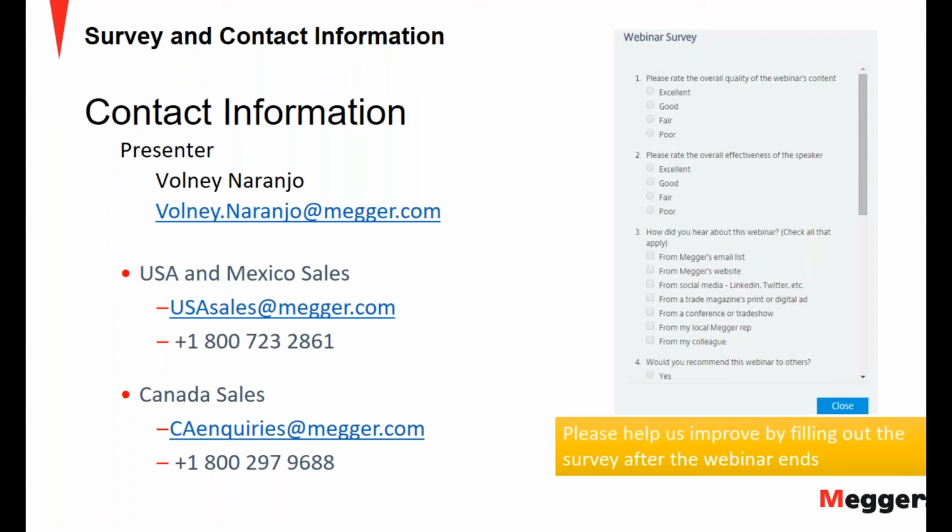A battery can store charge, but only for a certain time. If you don't keep it charged, it will tend to lose charge over time. So the battery is connected to a charger, and the output of the charger needs to be set at a specific voltage depending on the battery to which it's connected. That voltage is called the float voltage, and it needs to be at a certain value.